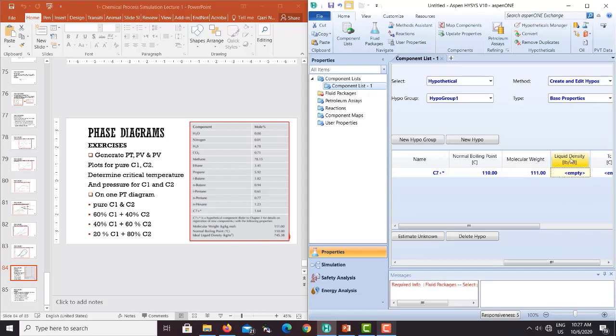the default density units are pound per feet cube. So we can either change it from the list, or we can change it here also. What we need to do is select 741, and here you can see the drop down menu. Just click that one and change it into kg per meter cube. So what this does is convert 745 kg per meter cube in terms of pound per feet cube and put it here. Okay, now this is all we need to provide.